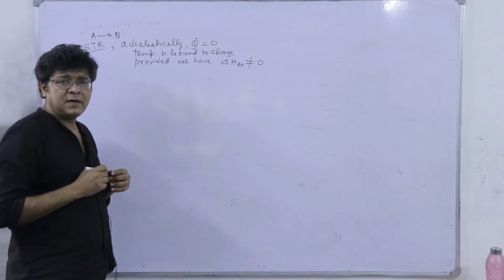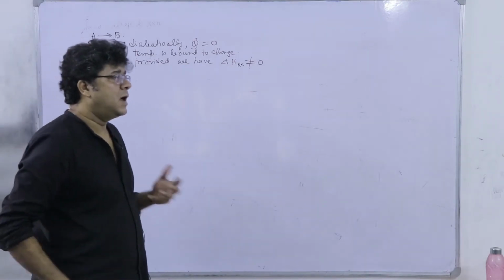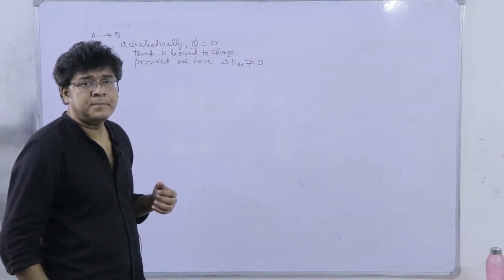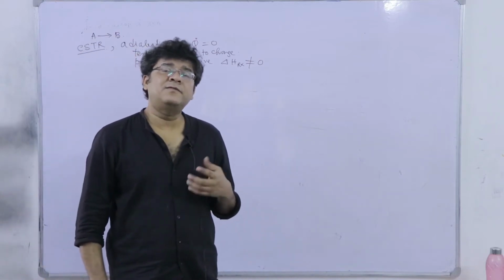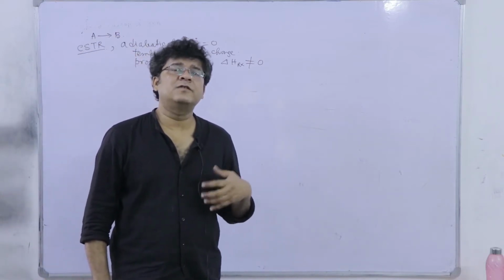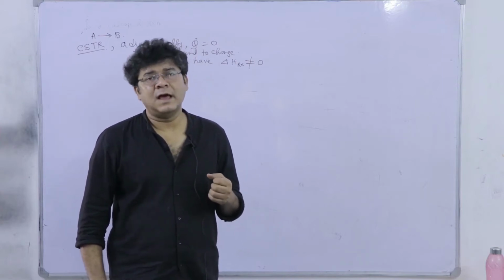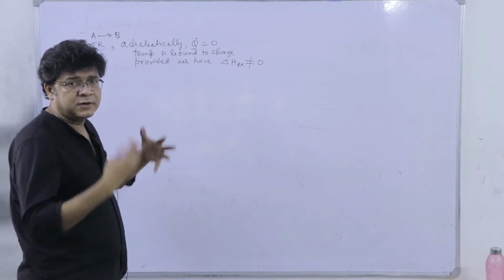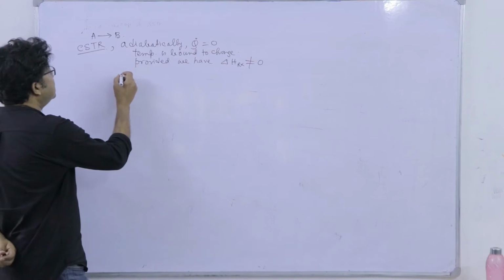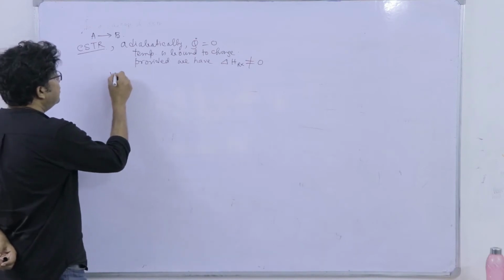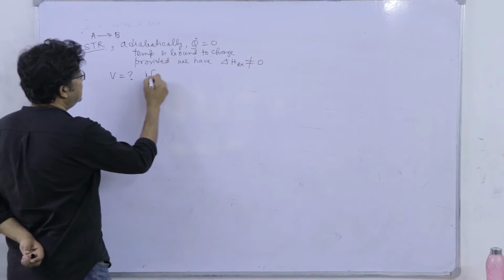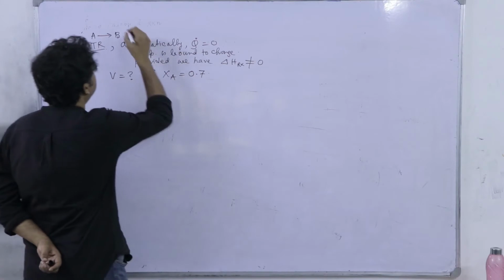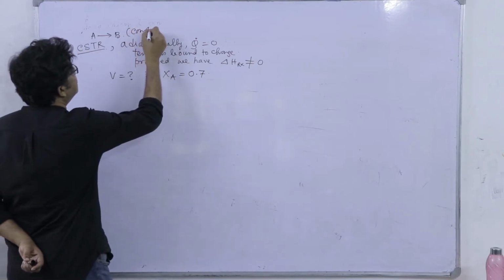So, so far we have discussed the isothermal reaction operation, or the reactor operation in the isothermal paradigm. Now we will think about what will happen if we operate a reactor adiabatically, which is closer to reality, and what problem we will face, particularly from the perspective of design. Like here the problem is, what will be the volume of the reactor if we want a fractional conversion of, say, 0.7 or 0.8, and it is a constant volume system.